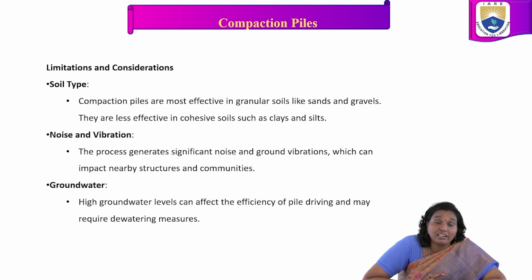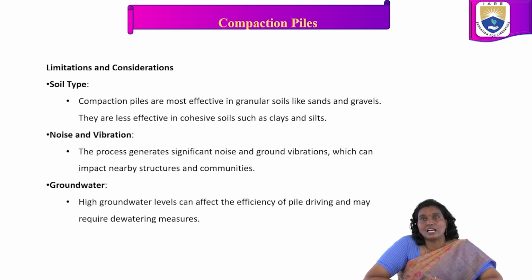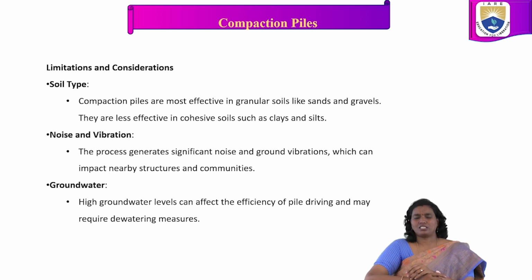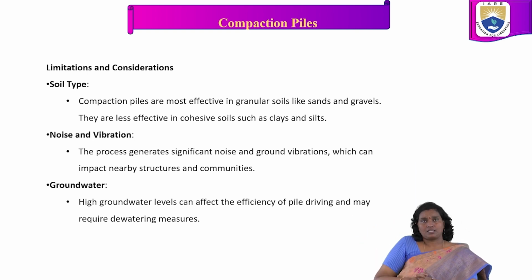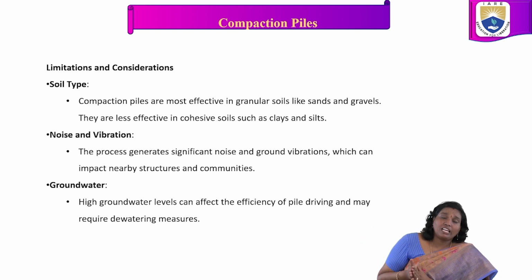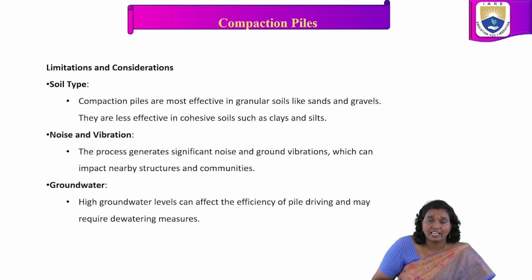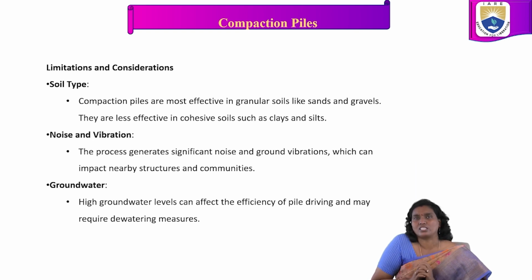Coming to noise and vibration. In this process, it creates so much noise and ground vibration, which can impact nearby structures and communities. Whenever we go in depth, it affects the surroundings very much. And one more important limitation for these compaction piles is that high groundwater levels can affect the efficiency of the pile driving and may require dewatering measures.